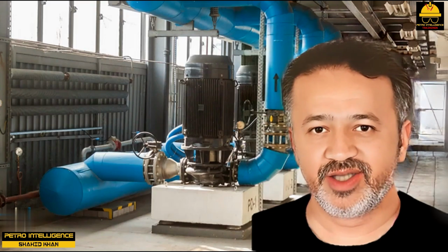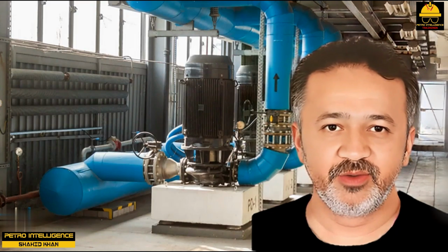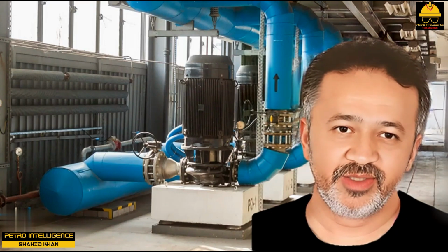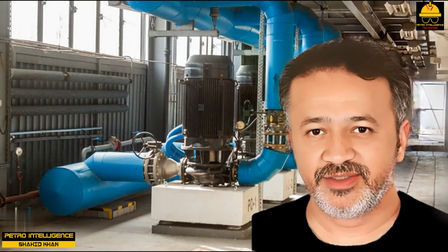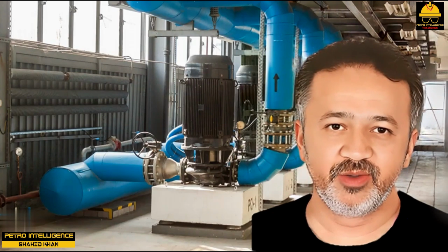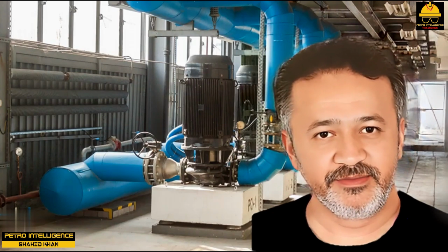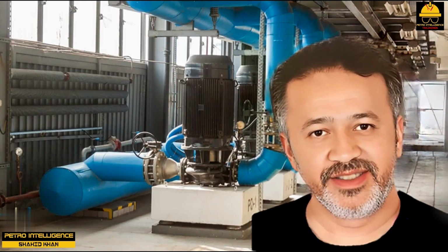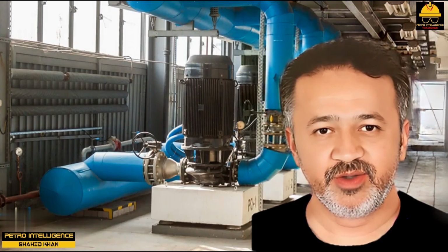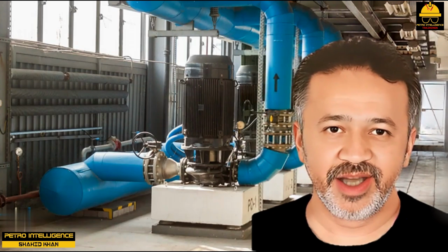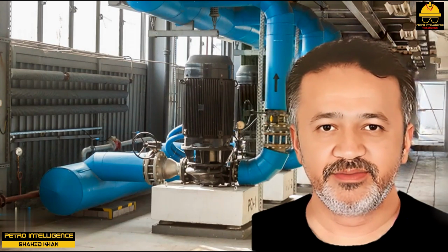You cannot see the direction of rotation of a pump, but if you touch a pencil to the spinning shaft, you can feel the direction of rotation. The correct direction of rotation is indicated by an arrow stamped on the top of the pump case. There are right and left-handed pumps. So, two otherwise identical pumps may have opposite directions of rotation.